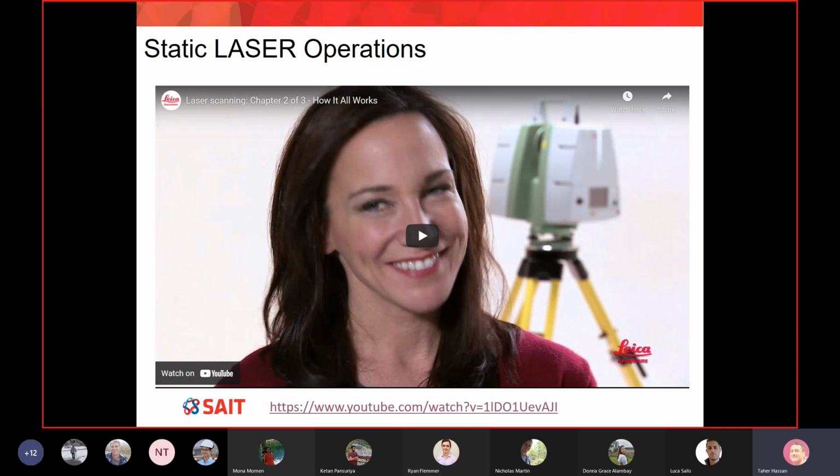One more thing, I'm not sure if you got it already from the video, is that a laser scanner can give you only X, Y, Z, 3-dimensional information. That is unlike photogrammetry, which by nature gives you X, Y, Z in addition to color information. So at the end, you get a colorful 3D model colored with the real texture of reality. In laser scanning in 2021, all the new scanners come with a built-in camera.